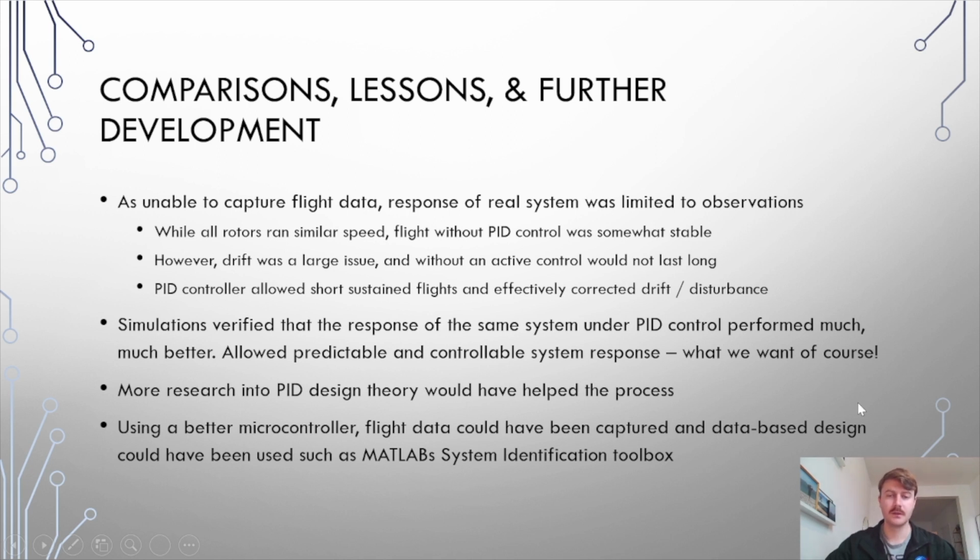So I was actually not able to pull flight data out, even if I was able to store it in the program. So at the bottom here, that mentions that I could have used the System Identification Toolbox in MATLAB and done some data-based design and use the flight data to help develop a model for the system that I actually had, which would have given me a better valued transfer function for the physical system, for the frame, for the drag from the flight data.